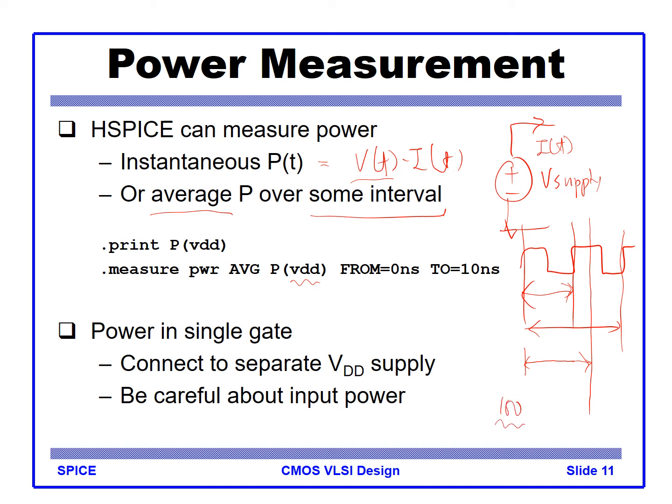For example, if you average over 100 cycles and miss the right time point by 1 cycle, you will get a 1% error in your measurement. As long as you are okay with that measurement error tolerance, it will be fine.